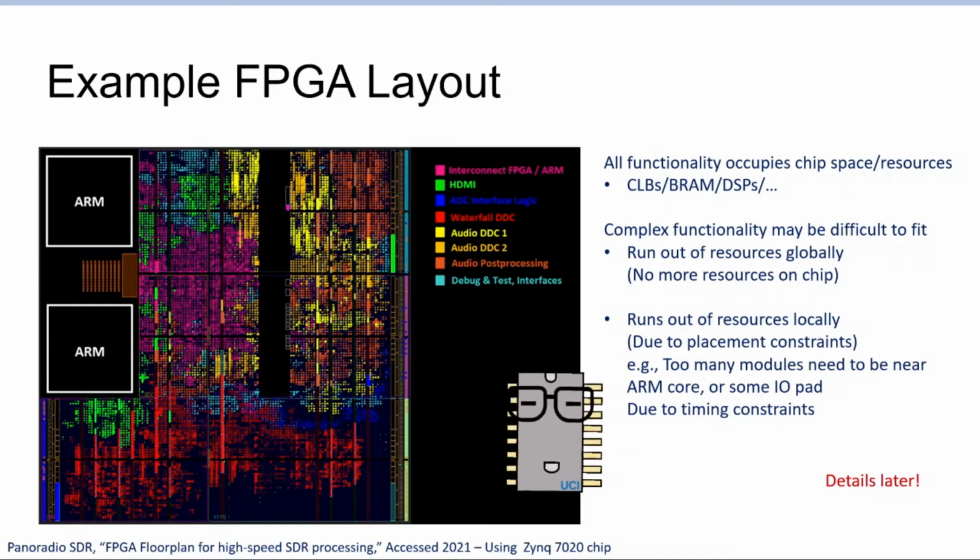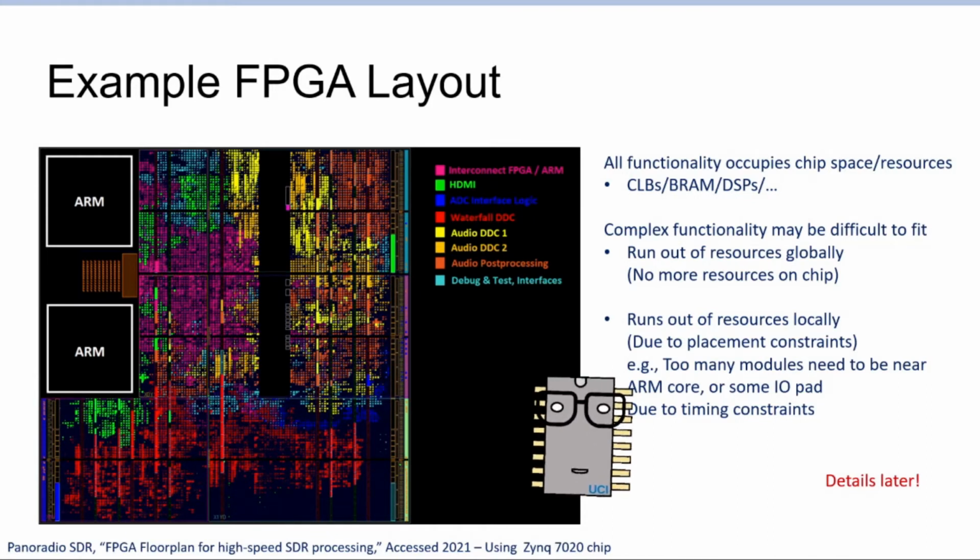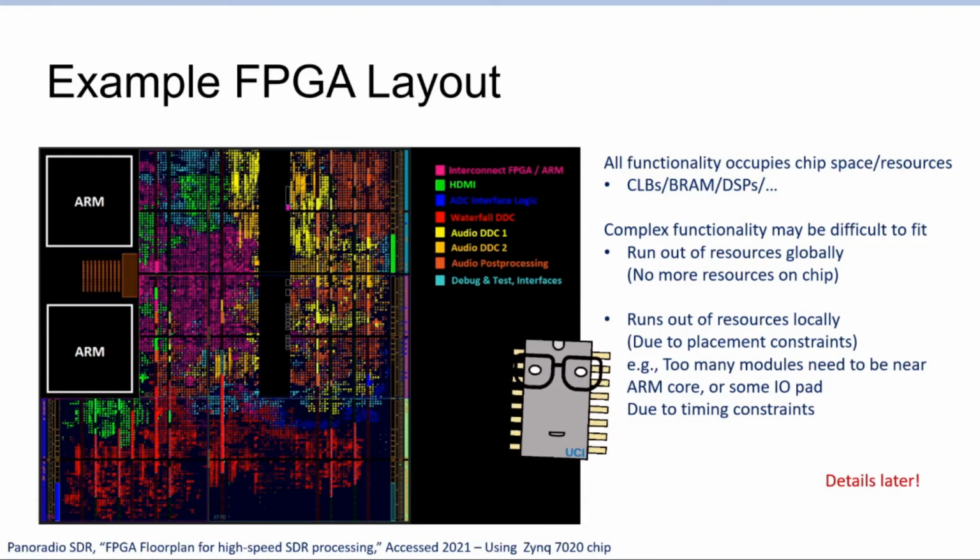And if there's too many of them, and there's other things occupying the space, the tool might not be able to put everything in a close enough location to meet timing. Or it might run out of resources. If something like that happens, you might run into a placement issue, and compilation will fail pretty much.